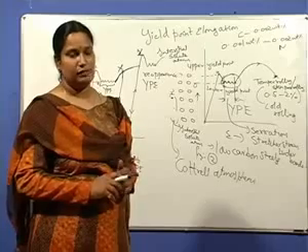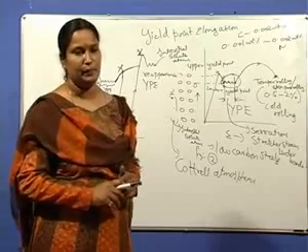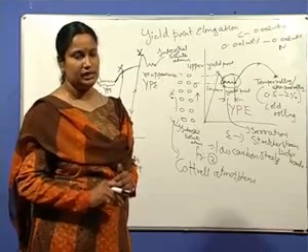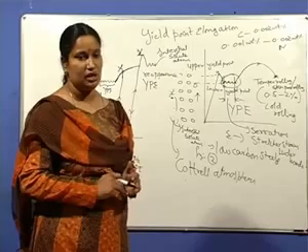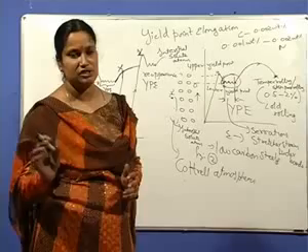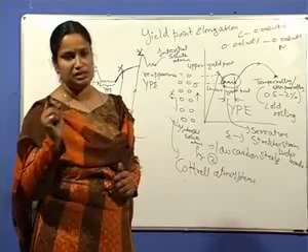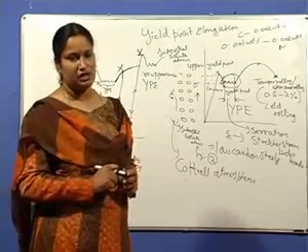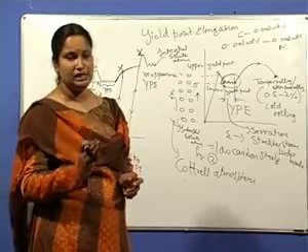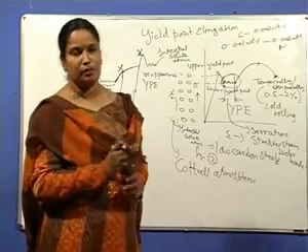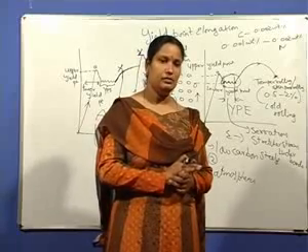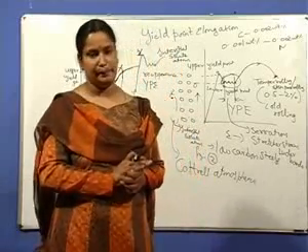Dynamic strain aging is the one seen at intermediate temperatures, around 100, 200, 300 degrees centigrade, at slightly higher temperatures. During deformation itself, serrations occur in the stress strain curve. Very fine serrations occur continuously in the stress strain curve. That is known as dynamic strain aging. Strain aging that occurs during deformation is known as dynamic strain aging.